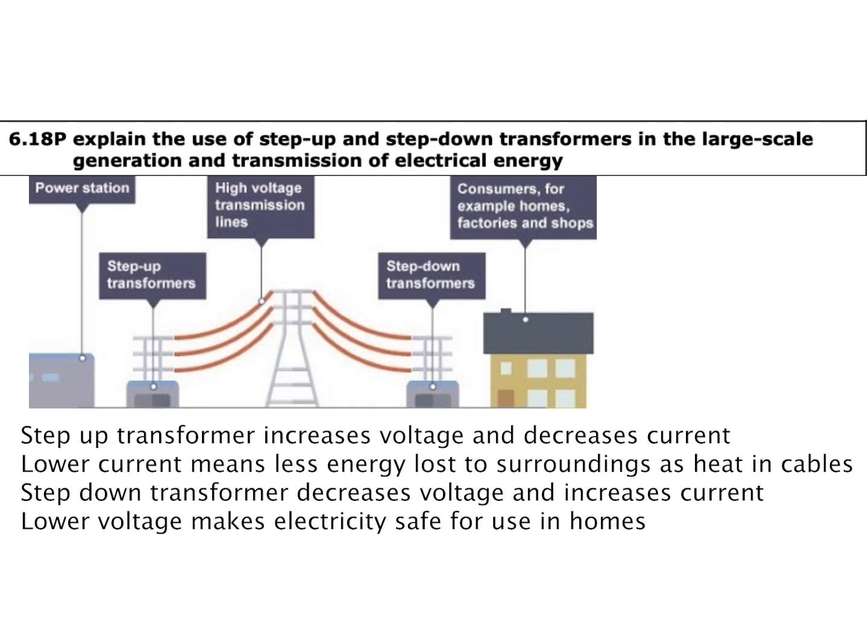Having large amounts of current causes large amounts of energy losses as heat. So if we increase the voltage, we will therefore reduce the amount of energy losses in our transmission lines. However, we don't want kilovolts going to our consumers and homes and factories. That would be unsafe. So we use step-down transformers to bring the voltages back to safe levels for consumers.